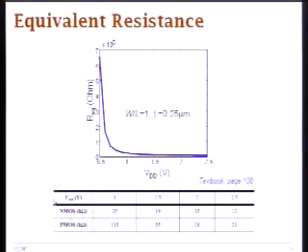These are some of the values for NMOS and PMOS for the technology that we use in the class, and what you should remember from this table is just the order of magnitude and kind of values that you may expect in practice when designing circuits in this technology. So it's about kilo ohm, tens of kilo ohms, that is pretty low resistance that's considered